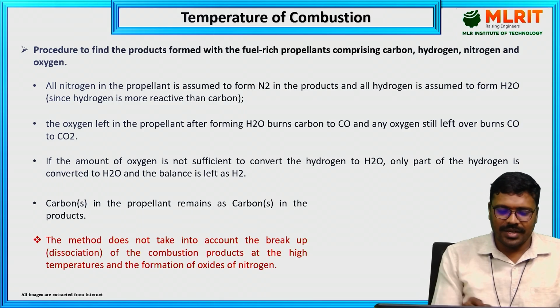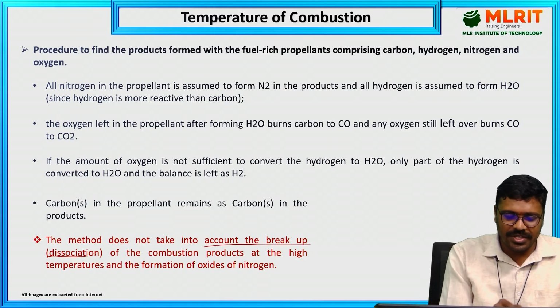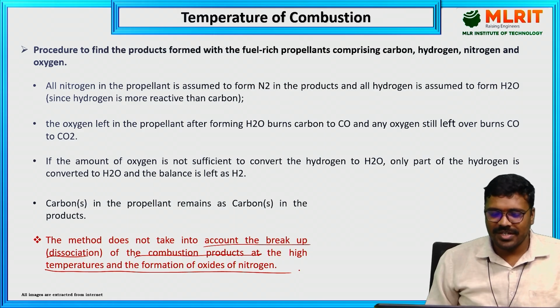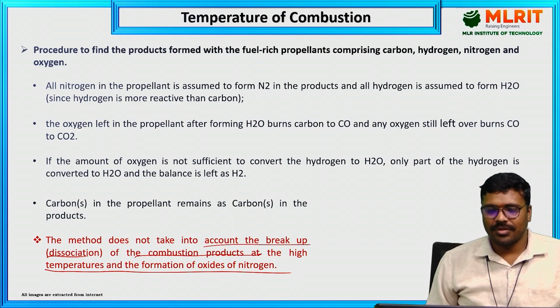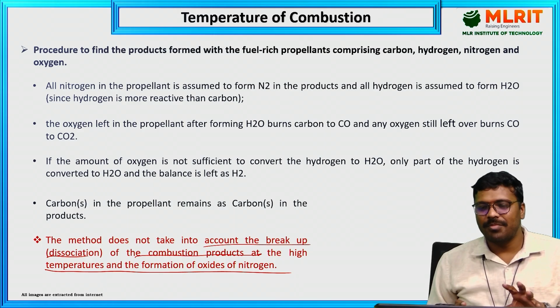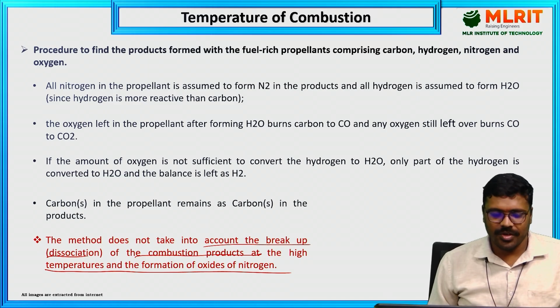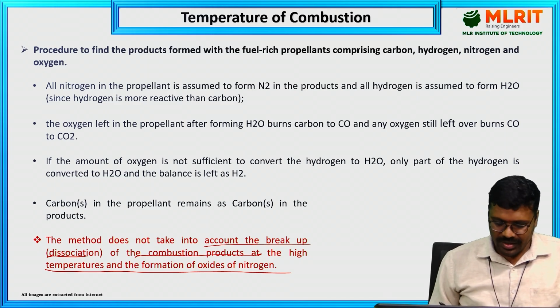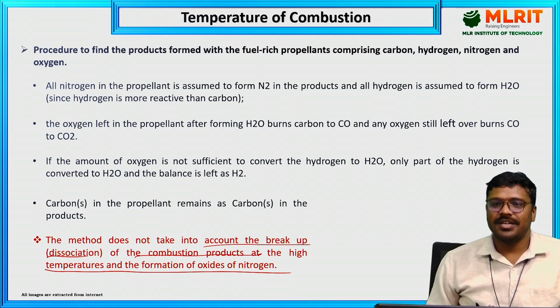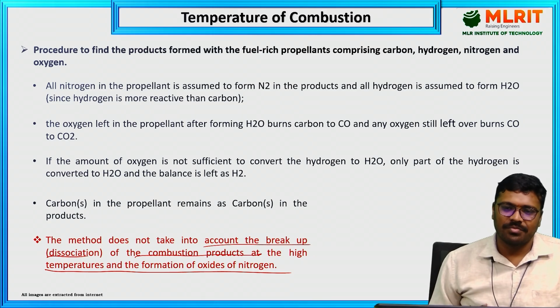The method does not take into account the dissociation of the combustion products at high temperatures and the formation of oxides of nitrogen. So this method will not be applicable for high temperatures, as it will not consider the dissociation that happens at high temperatures.